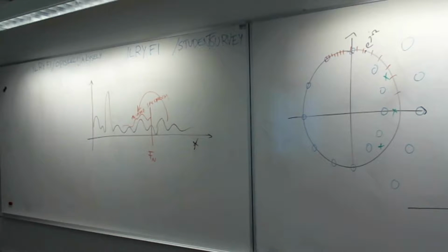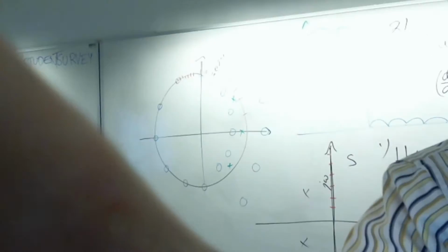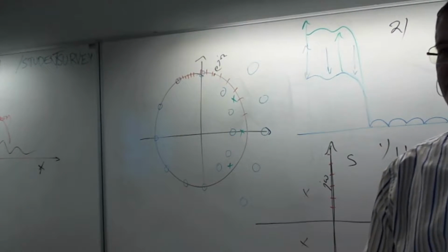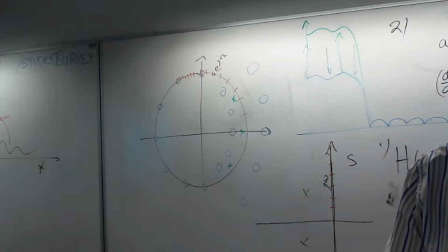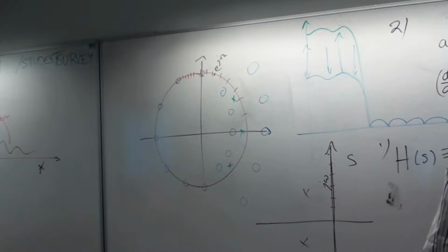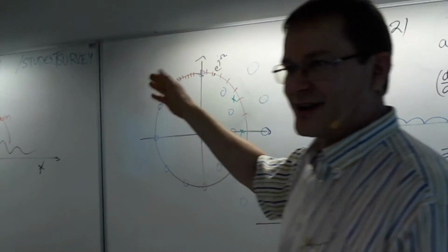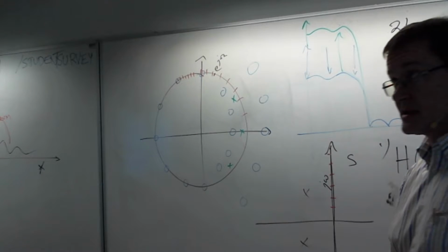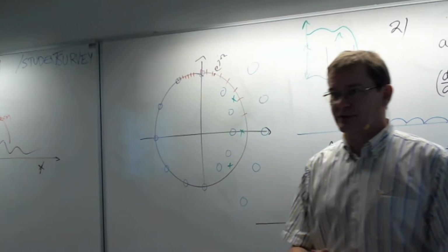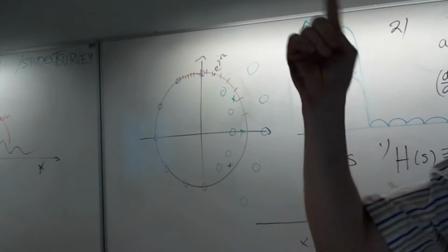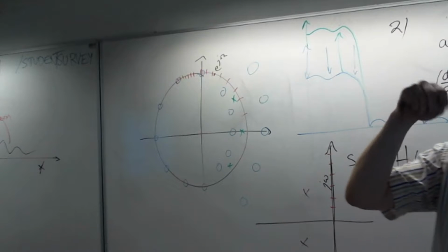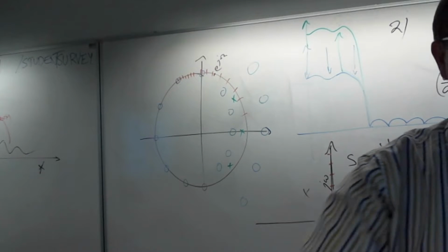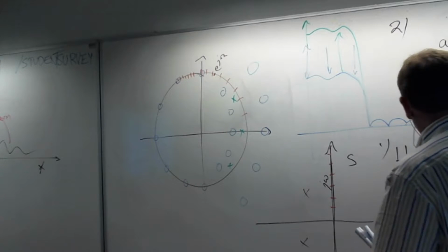Another method: it's possible to create that with a really high sampling frequency first, then you have discretized it and you filter it again. Yes, decimate it. Do some digital filtering and drop the sampling rate. It's the same as what the sigma delta A to D converter is actually doing. It's a 1-bit conversion at the beginning. This A to D conversion for audio.